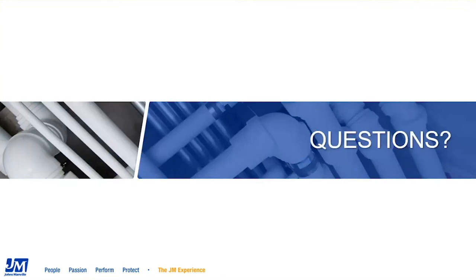The first question is for you, Paul, and that is, does JM offer preformed and/or prefabricated fiberglass fittings as opposed to field fabricating miters to match existing pipe insulation? Thanks, Kim. To address that, we offer pipe sections, but we don't offer any prefabricated fittings for use at the elbows. The most common solution I see would be to utilize JM's Zeston PVC fittings stuffed with insulation inserts.